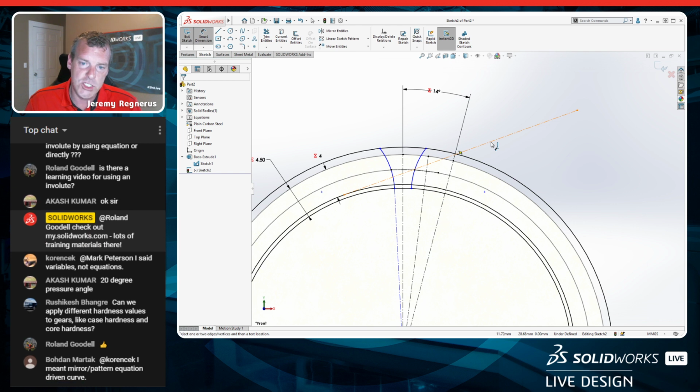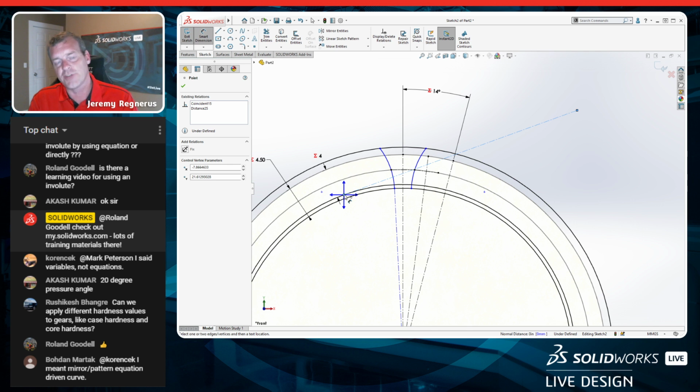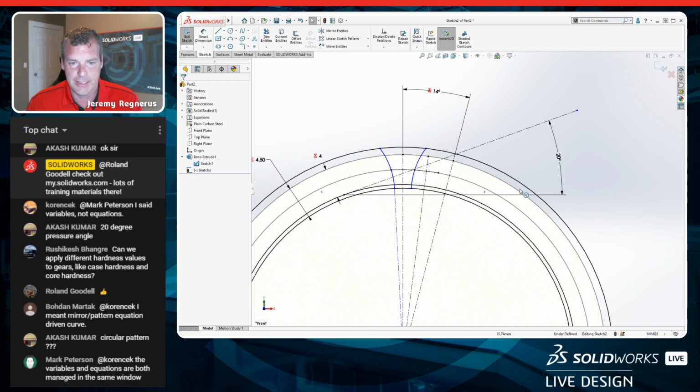I want to dimension this line, and I want to reference this endpoint. Notice when I do this, I get a little crosshairs on that point that I selected. It allows me to choose a cardinal direction, north, south, east, or west right here. I'm going to go ahead and choose east, and I can place this 20-degree value without selecting anything else. That to me is pretty cool. I don't actually need another piece of geometry. It knows to dimension it horizontally. So that's a cool trick. We'll use that again later on.